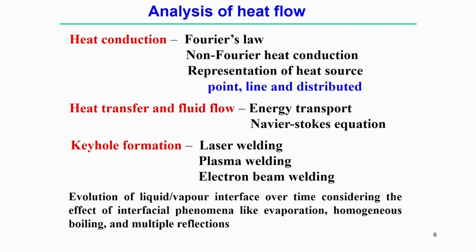And then for the material flow analysis, for the momentum equation, we generally solve the Navier-Stokes equation to estimate the velocity field within the small weld pool. Of course, as compared to heat conduction, the heat transfer and fluid flow transport equations are computationally more costly, that means computational time will be more in this case as compared to the heat conduction equation.